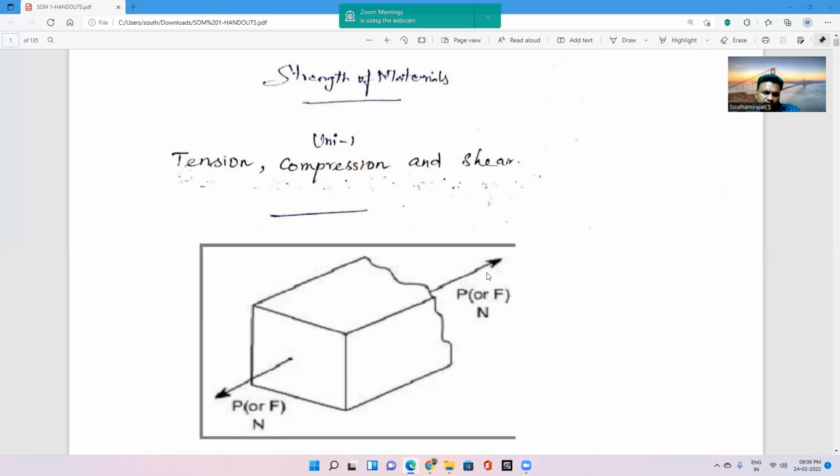because some materials can tolerate the compressive load, but some materials will not be able to tolerate it. For example, concrete is good in compression, so concrete can carry maximum compressive load up to the yield level, and even beyond the yield level up to the ultimate level. But in the case of a steel member, you can't expect that, because steel is good in tension, but very much weaker in compression, so the material will not take compressive load as much as tensile load.